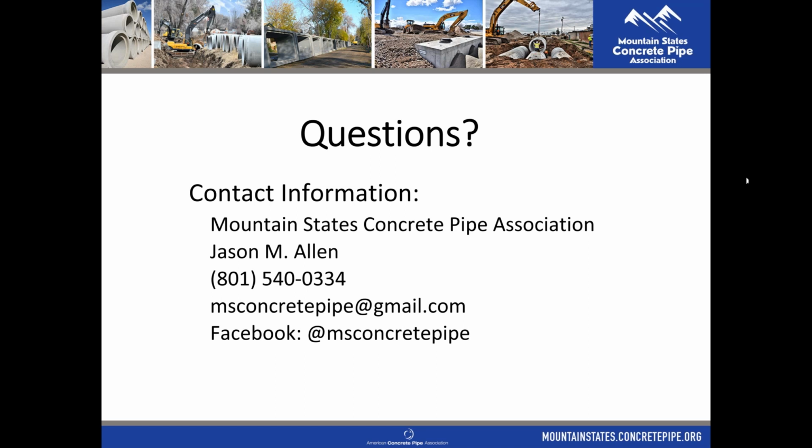What changes to the design must be made in the trench design? I think this again relates to the question of what we would change if they wanted to shift to a different material. Luis asked that question. Obviously, the trench design is going to change, because the pipe zone will change from spring line up to however many inches over the pipe you recommend as the design engineer after you've run your structural calculation. So the trench will have to change.